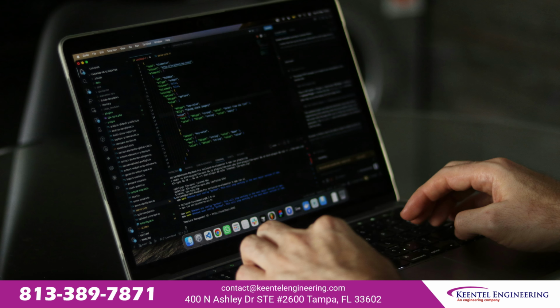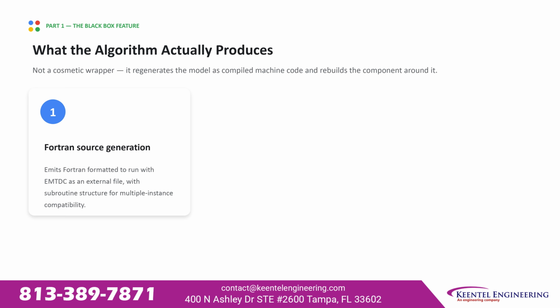Same PSCAD release, two complementary tools, two different directions. One keeps the model inside PSCAD but hides it. The other takes it out entirely. The black box feature is not a cosmetic wrapper. It regenerates the model as compiled machine code and rebuilds the component around it from scratch.